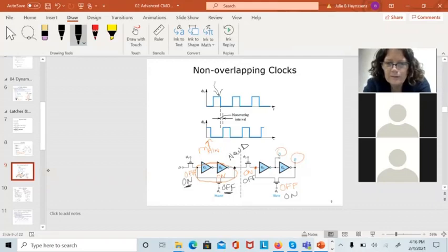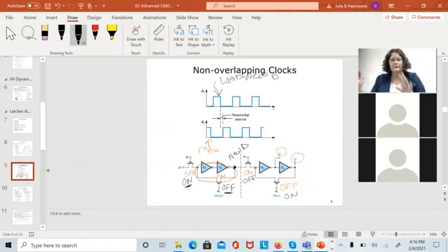This transistor is still off, so the new D is going to get stored right there. I haven't changed states yet. This is when I'm loading the new D in. And now I need yet a third color to get the flip and the flop.